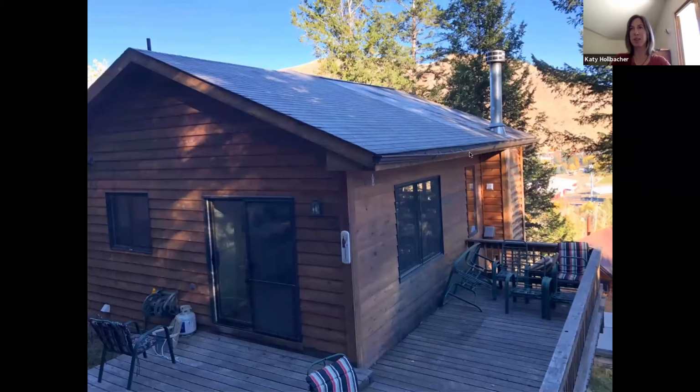And in the interest of everything we want to get through, rather than dwelling too much on this, another thing you'll see is the gutter has been misshapen here. So if you're on the inside of the house, what you would see is that there's a drop ceiling in this half of the roof. So this is all drop ceiling. This is an attic space with insulation at the ceiling level. This attic is supposed to be cold. Vented attic, this attic in theory should actually be cold. This is a cathedral roof that I believe is probably spray foam, but then we see all these melted areas.